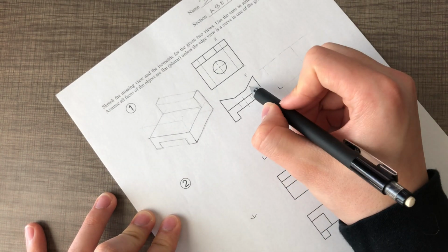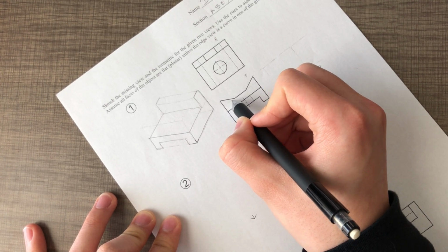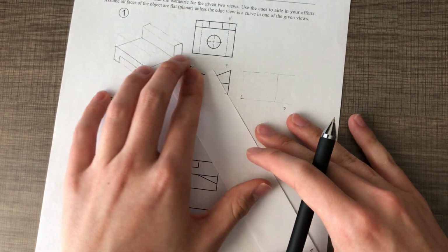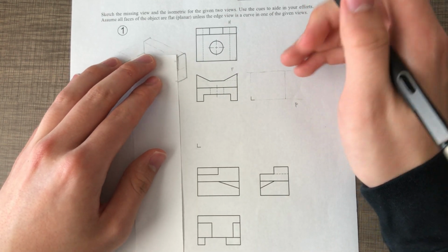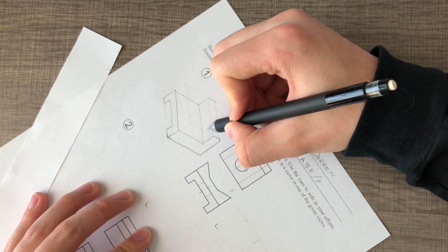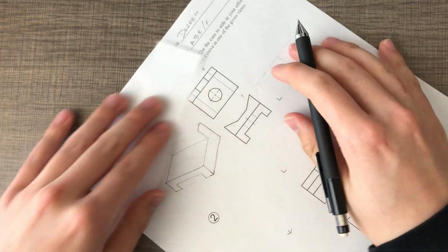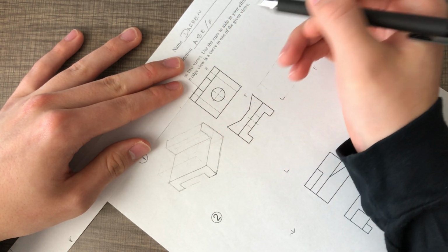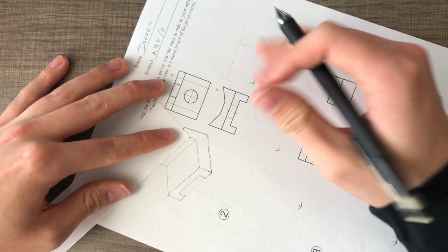Well, I know that this distance is how far these kind of ears go back down. So this distance here, right? So I'll take my trammel. I can take this distance. Bring a construction line across here. How far do they go over? Well, I can see that here, right? On the top view, if I trammel this distance, that's how far they go over.